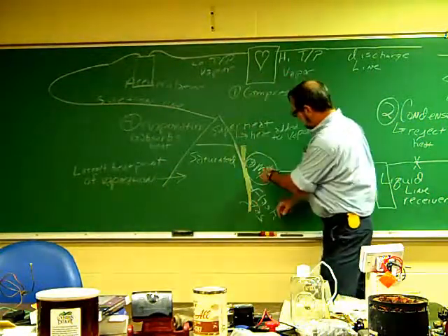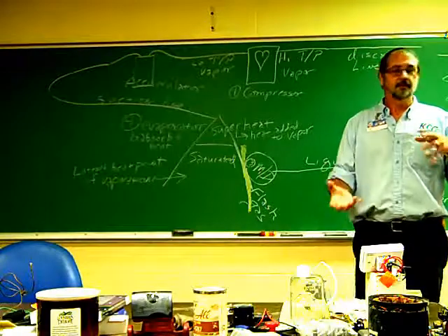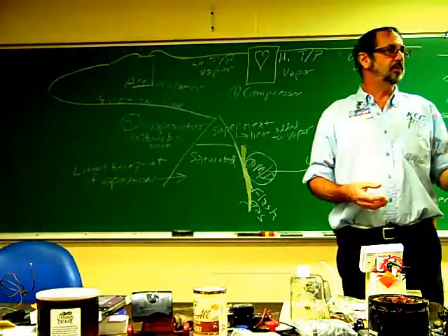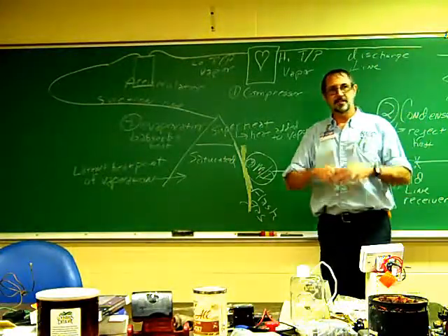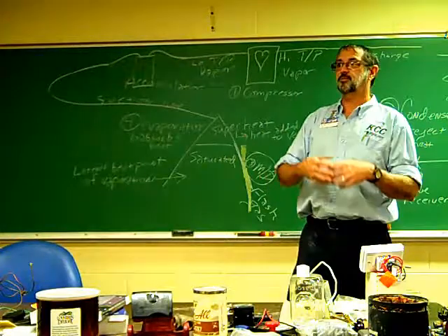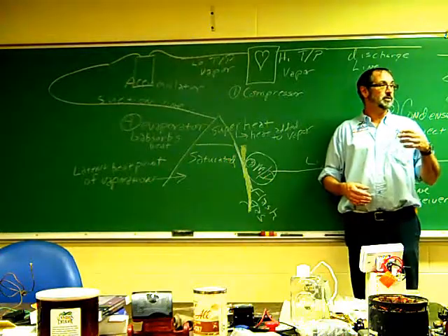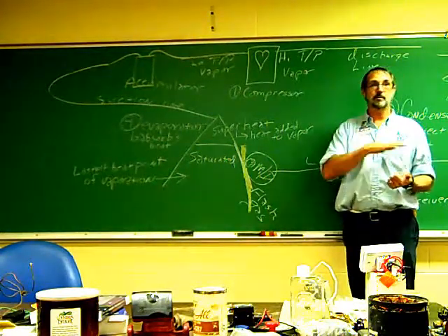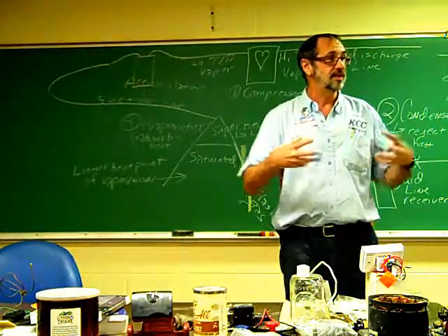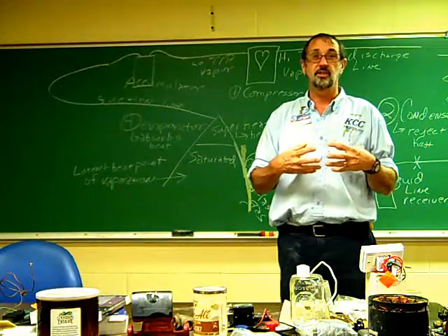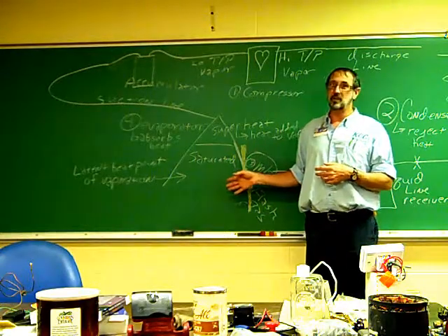Also remember, at the outlet of this metering device, we're going to have what is called flash gas. Now, if you remember flash gas, probably the easiest explanation is just when liquid bypasses the saturation state and gets to be vapor. There's a little bit more to it than that. It's in the world of physics, and we're not physics guys, we're heating and air conditioning guys. So that's all we're really going to remember about flash gas. It's when the refrigerant changes state from a liquid to a vapor, it bypasses saturation. You'll remember going back from our theory of heat that saturation is where the majority of the heat is either absorbed or rejected. In this case, when we bypass saturation, we don't absorb quite as much heat.